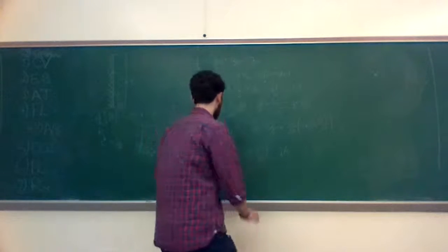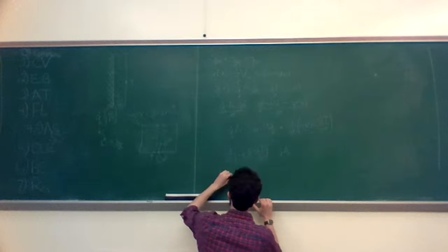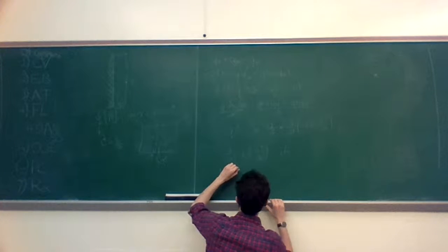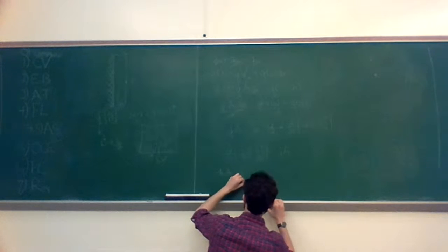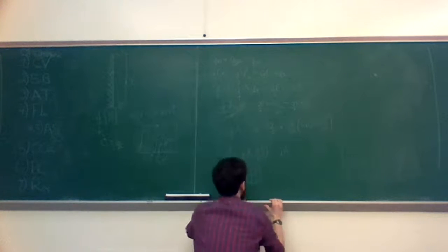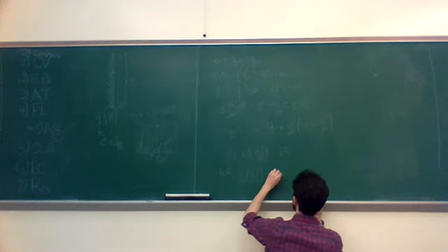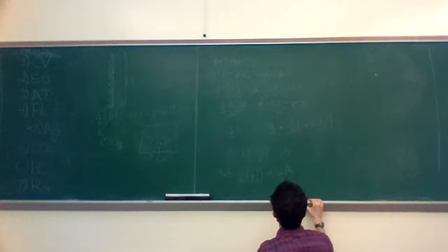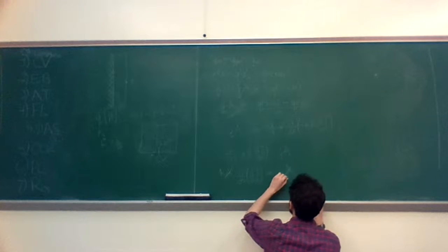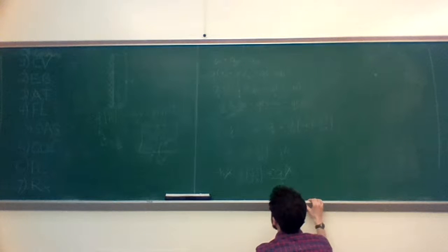So we can take all this stuff out, and now it's negative kA times d/dx of dT/dx. We'll write it out longways: d/dx of dT/dx equals q-dot times A. Okay, what next? Cancel the A's. Well, we'll bring the negative k over. So now we've got d/dx of dT/dx is negative q-dot over k.